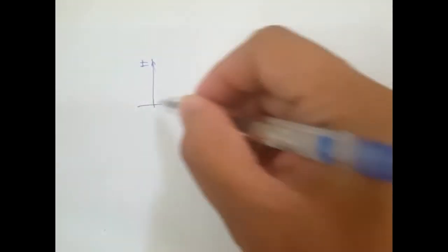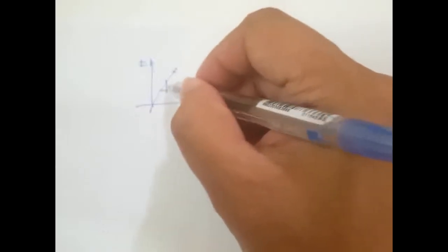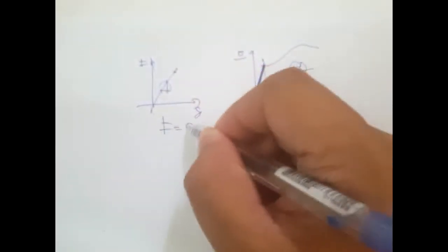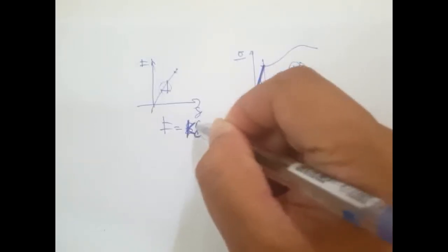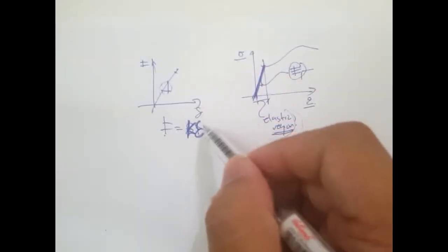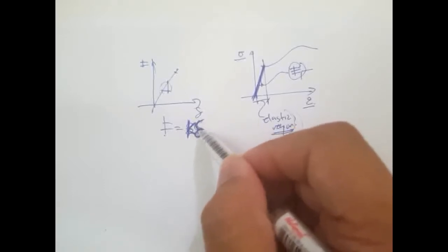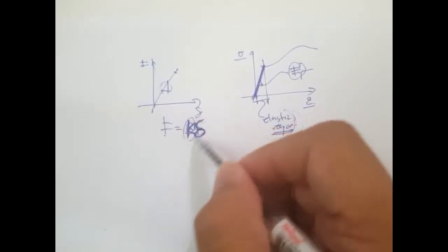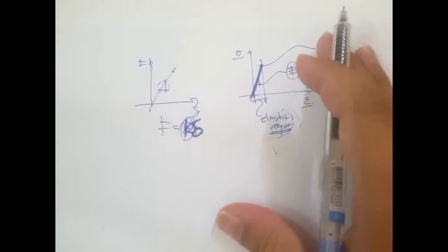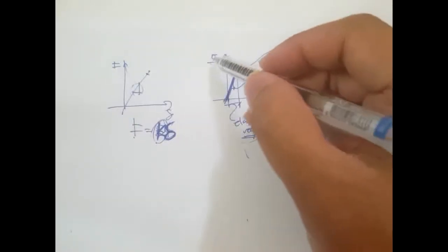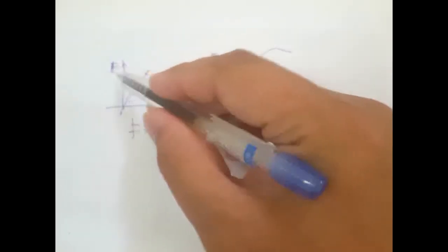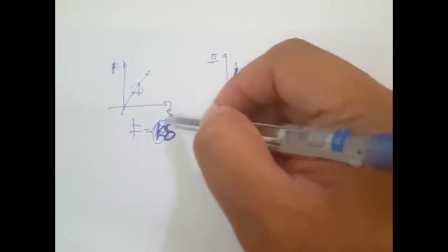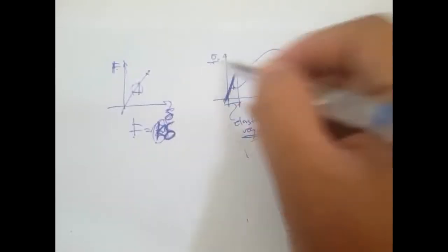So if you recall in our strength deformation curve, right? This proportionality constant is called stiffness. So force is directly proportional to the deformation, and this proportionality constant is what we call the stiffness. When using the stress strain curve, if we divide this force by the area and we divide this by the length, then we get the stress strain curve.